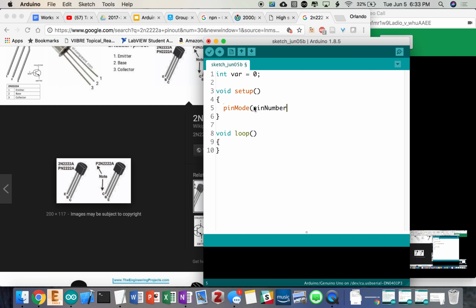If you want to make an LED blink, we can just use digital pins, for example. To set up digital pins, we first use a function called pin mode. Digital pins can either output information or read in information. For reading in, we'd use pin mode input. But since we want to make an LED blink, instead of declaring them as input, we'll declare them as an output.